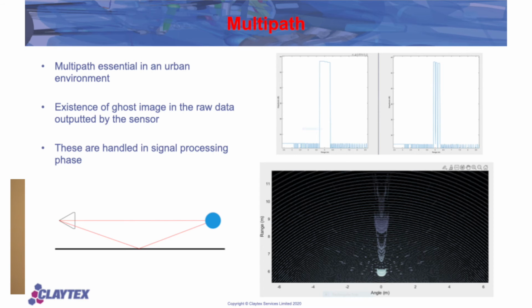The first one is the normal sphere, the second one goes like that and back like that, and the third one goes down to the floor, back up, and back down to the floor. So there's a bit of a delay: the radar sees the sphere a bit further away, and it's illustrated in the second picture. It's emphasized, it's not normally that strong, but it's just so you can see two spheres over there. That's something that we need to take into account.